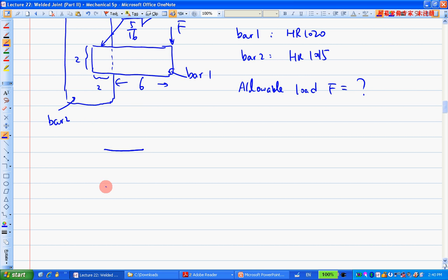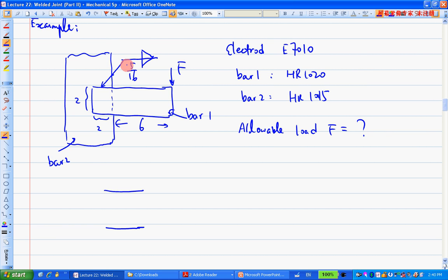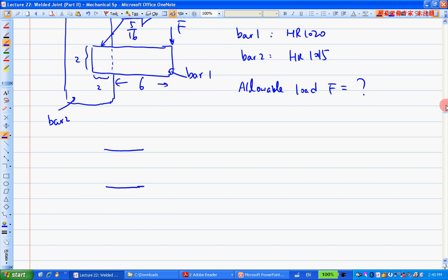So draw the geometry of the weld first. It's 2 horizontal bars, as indicated, because the 2 triangles here mean you have weld. This is the arrow side, and that's the other side, right? So you got 2 basically symmetric welds. And 5/16, remember what that is? H. That's right, that's H. So you need that information.